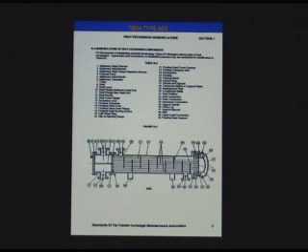With an S-type head, you would require a full diameter channel cover. Actually, it's larger than full diameter because you have to be able to pull the bundle. You have to take off the shell cover to access the floating head bolting here.